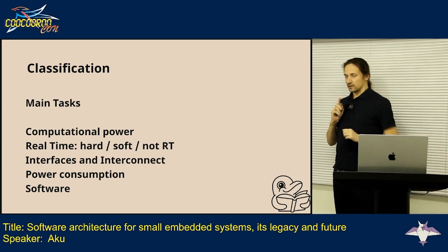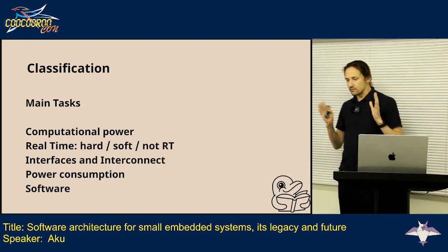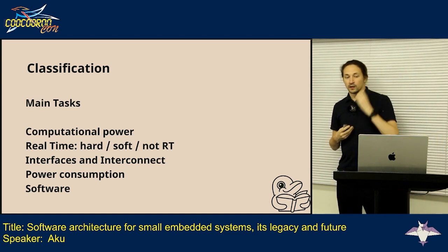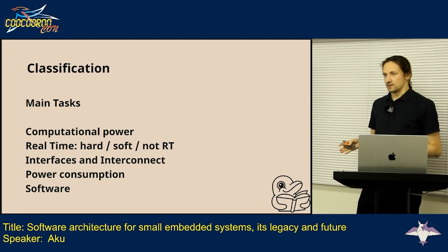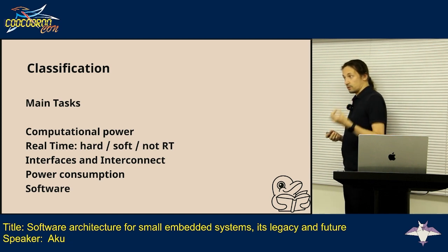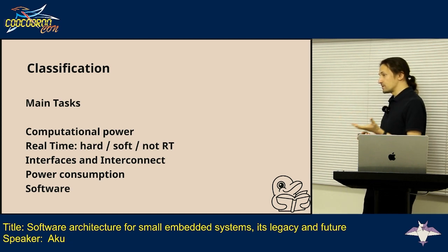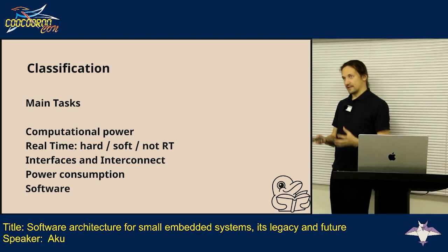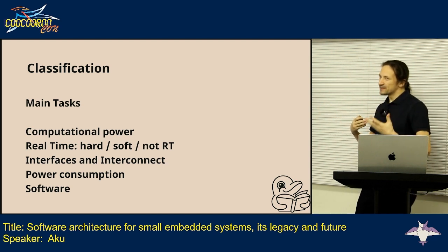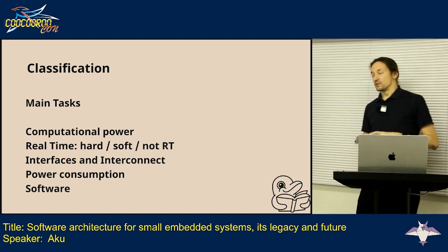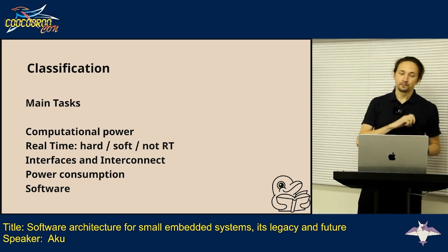But you still would like to at least keep some kind of real-time, to react on some events in some predictable fashion. And then we have non-real-time systems, a system that doesn't require immediate reaction on the event. Those systems can be built with general purpose CPUs, like big ARM cores. A good example is Raspberry Pi. So yes, it has GPIO, yes, it can be connected to something, but the reaction time usually doesn't satisfy either soft real-time or hard real-time.